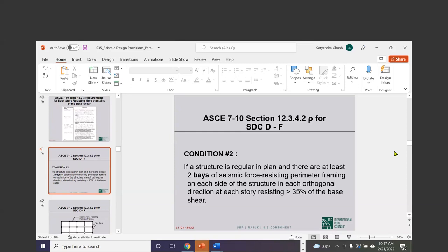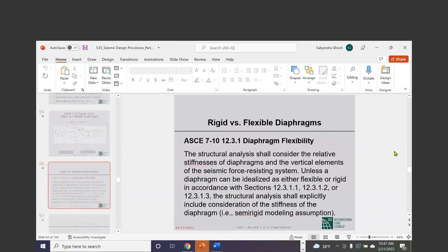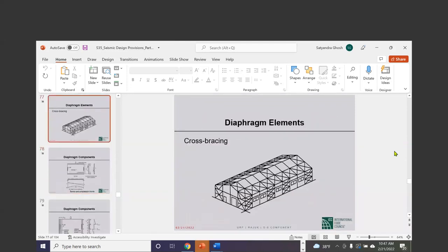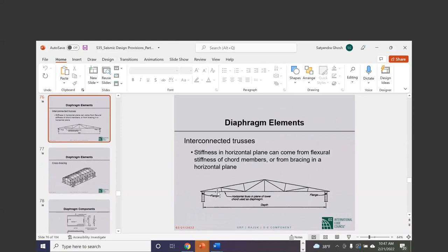And we use horizontal bracing systems as diaphragm. That you mentioned in one of the slides. Yeah, if you can imagine on this horizontal plane into the screen, horizontal bracing, that would serve quite well as diaphragm. As I said, we saw in and around Santiago, Chile, the industrial buildings were many of them that way. That was their diaphragm.